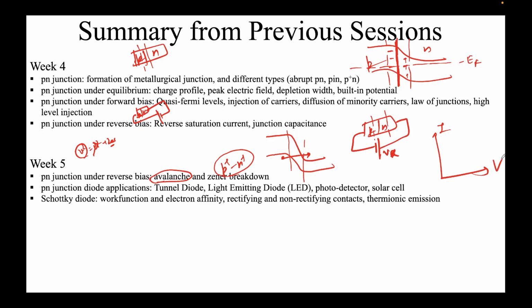saw the IV characteristics look something like this. First, the current increases due to tunneling, then the current reduces because tunneling has started to reduce, but the typical drift current has not increased that much. And if you increase the forward bias of the p-n junction further, the diffusion mechanism will now kick in, not the drift. Here we have something called negative resistance, which is a unique phenomenon of the tunnel diode.